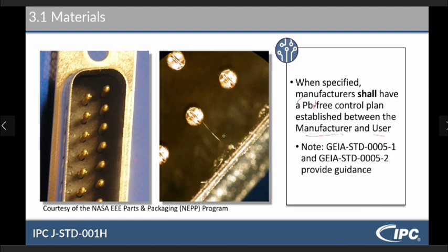This right here, if you can see, looks like a little white line, almost like a scratch. That's actually a tin whisker. When they're lead-free, there's more tin, and it tends to have little whiskers, like little fuzzy lines in the solder. There is a link here that you can go to if you want to learn more about tin whiskers.